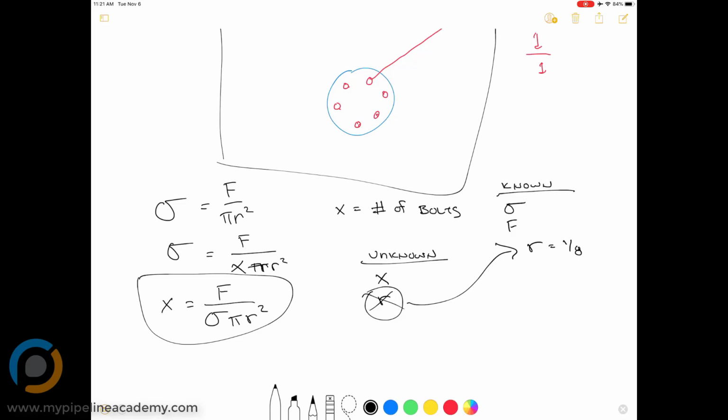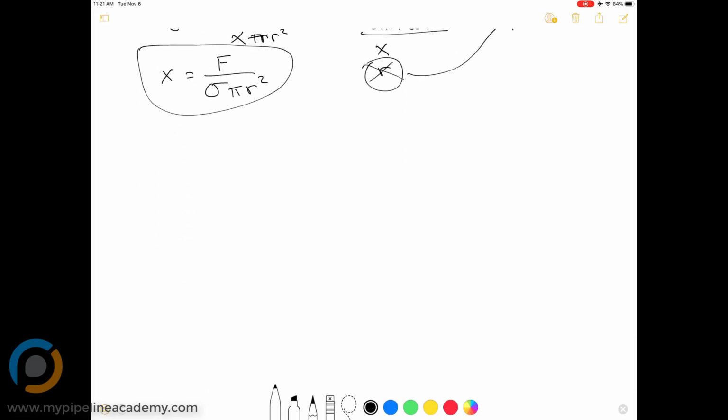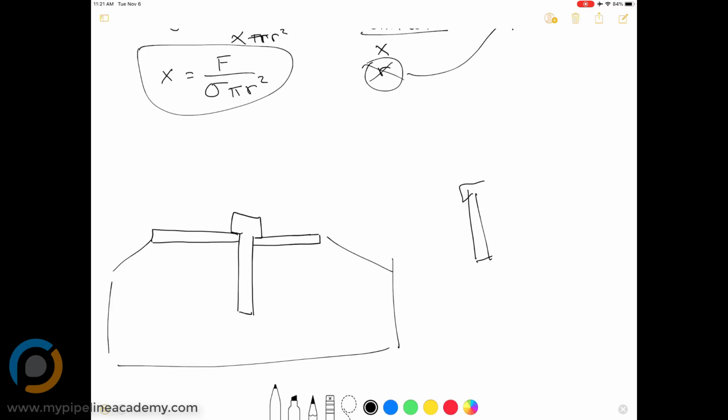But now I'm thinking about the dimensions of a screw. Let's say this is the flange, I suppose, and the light is here. Where is the most stress on the screw? Because when we say the diameter, we're looking at the diameter here. And that is correct, because we're looking at the diameter of the place that has the least area, and least area means that there's going to be more stress. So we're doing the calculation for the area that has the most stress. That would probably be here, right? Right, because this is going down.